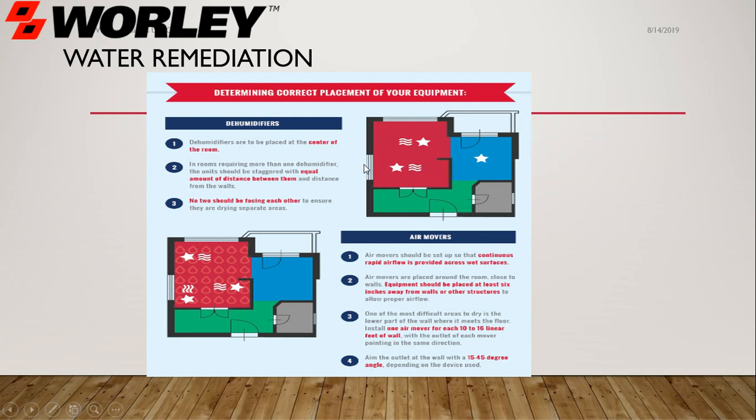The more air movement, the more friction. The more friction, it heats up the air. The hotter the air, it will move to the cool. A dehumidifier is built with a condenser inside. It's a cooling condenser. So the hot air blows over the cooling condenser, it condensates water, goes to a drip pan, and there's a discharge line out of the dehumidifier, and that's the drying process.